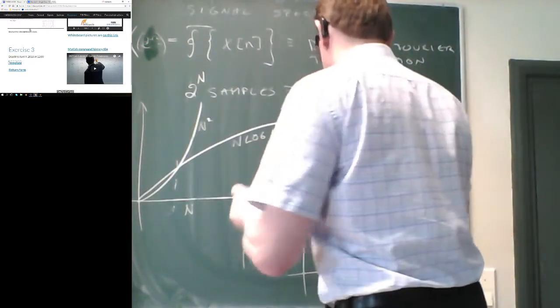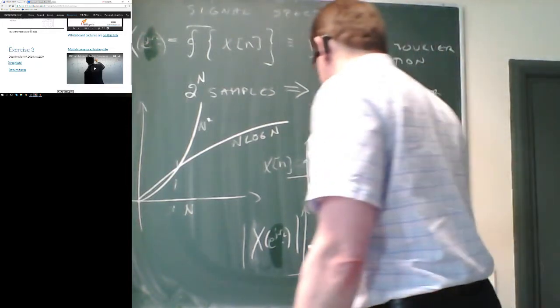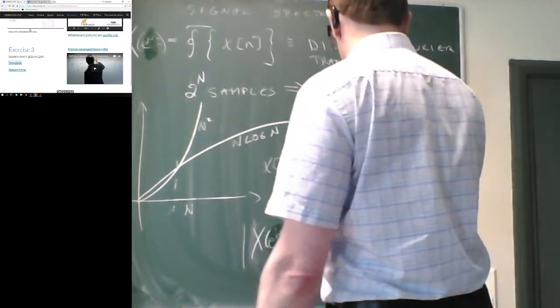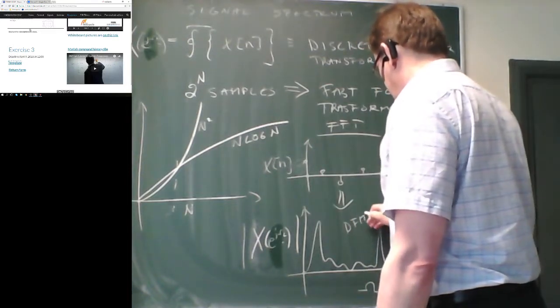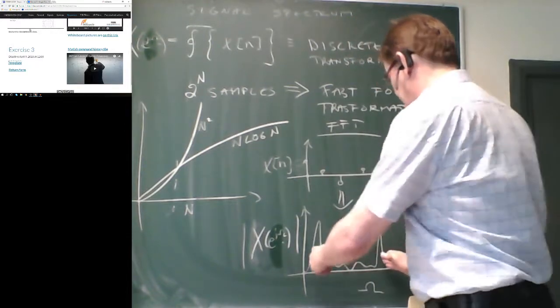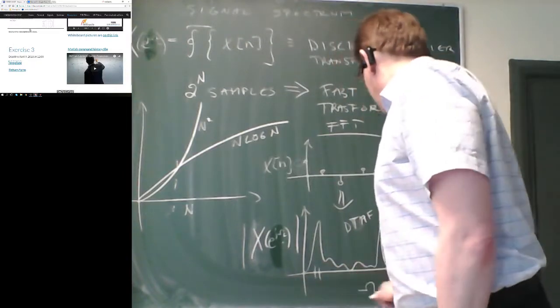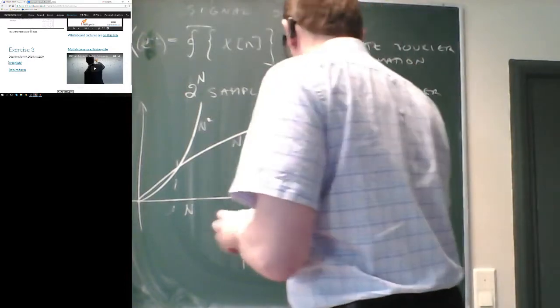So the amplitude spectrum of this signal would look like whatever it looks like. For example, this could be a DTMF, dual tone multiple frequency, sampled data from that one, showing that we have these two signals there, and the frequencies of those tell you the key code for that DTMF signal.